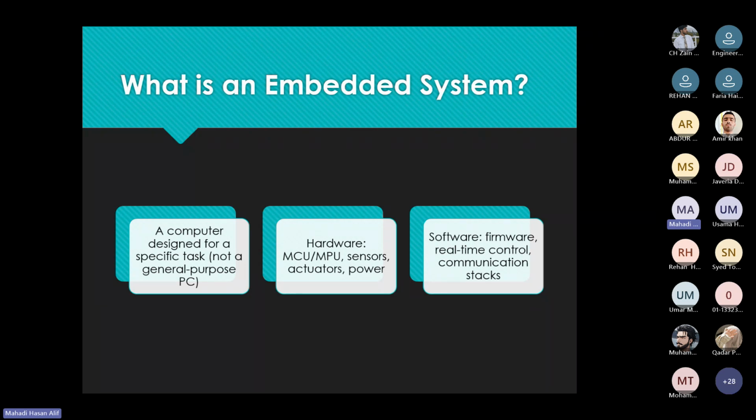I2C and SPI are used for the sensors, whereas we have UART communication for the LEDs. We have USB communication between the PC and the microcontroller. Then we have CAN communication with the motors.